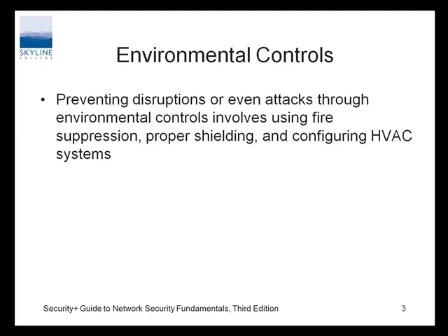Electrical fire. What are we going to use on an electrical fire? Clean agent. Well, that's good. What clean agent are you going to use? Probably carbon dioxide. What's the problem with CO2? CO2 flooding is what they generally say. What's the problem with CO2 flooding? It puts the fire out, but it also puts you out. It kills you. Okay? You got the fire out.